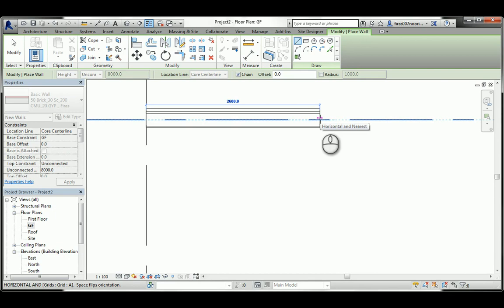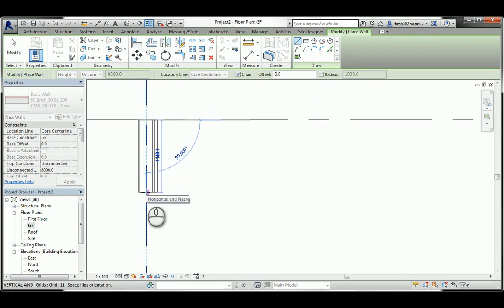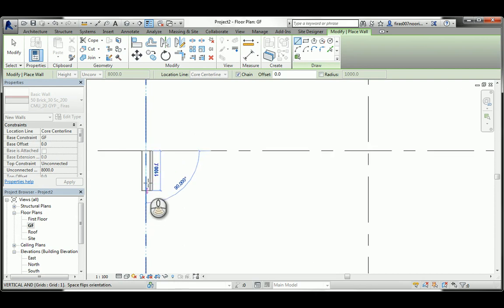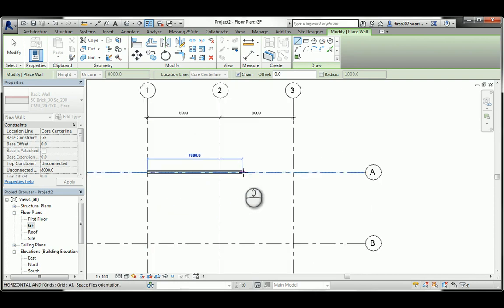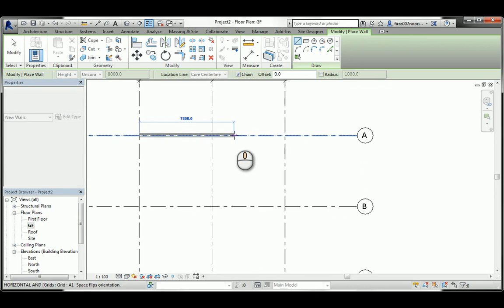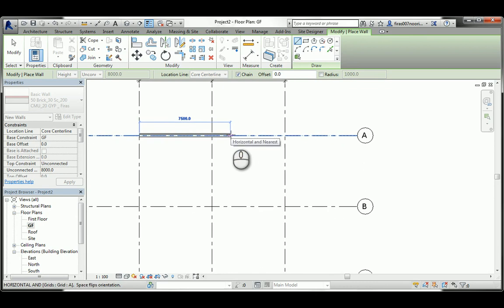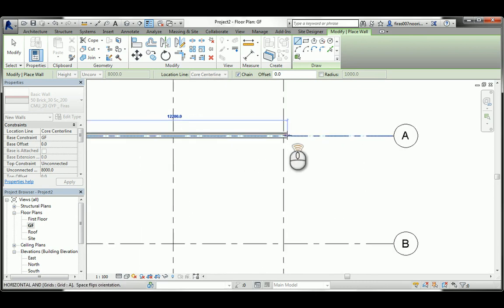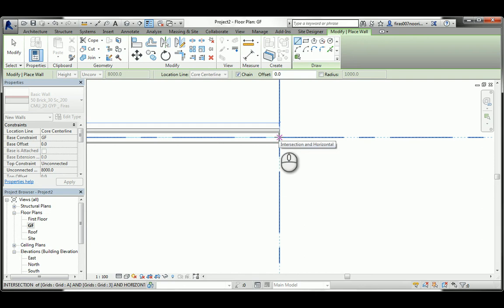See, now it's been proposed to be correct, and the external layer, which is a brick, is to the outside, while the gypsum board is to the inside. Careful, if you do it the other way around, the brick will be inside and the gypsum will be outside. That's very wrong. So yes, it differs if you go counterclockwise or the other way around. So be careful. Anyway, zoom in a little bit. See, now we're doing it okay. You saw the intersection. Click.